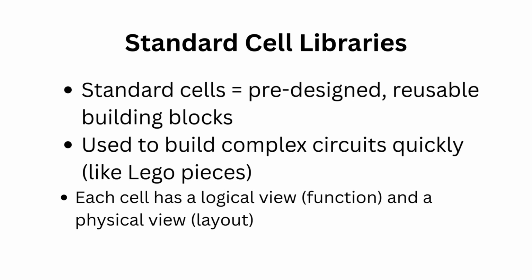Standard cell libraries. When we design chips, we don't draw every transistor inside. Instead, we use standard cells. Those are pre-designed, pre-verified building blocks like inverters, NAND gates, or flip-flops. We combine these cells to build complex circuits, and EDA tools place and connect them automatically.